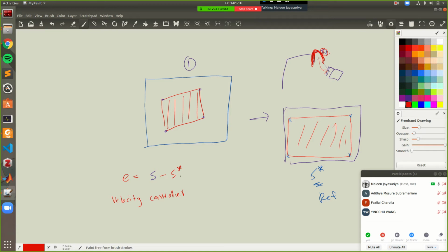So what we need to do, just like in the PID controller, is find a relationship between the parameters that we can control, which is our input, and this error. We created a KP term and a KI term for that error, and we controlled our input in a way that is related to these errors. That's pretty much what we have to do here as well.